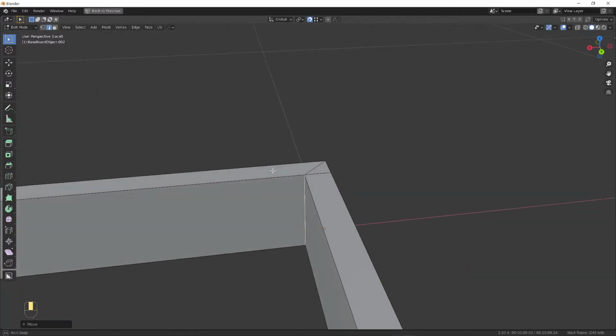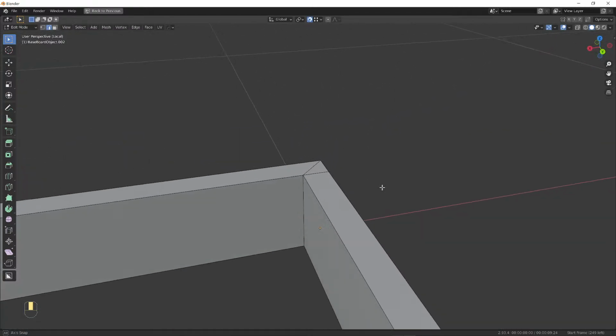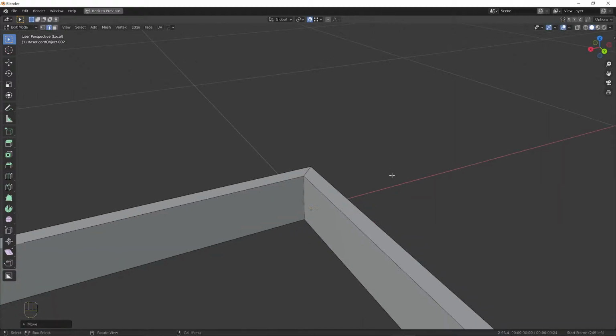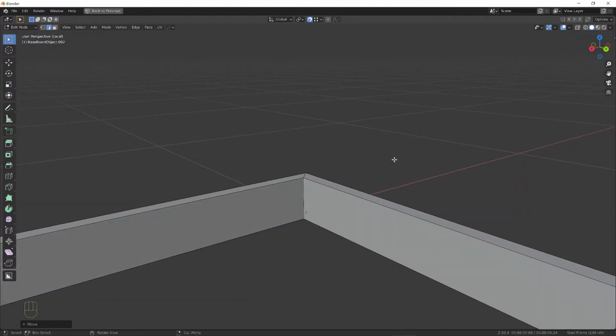Okay, I'll do the same thing here. Select this. I'll press G, in this case X, to move along the X axis. And then I'll hover at the vertice that I want to snap to, in this case this one. Okay, I'm going to press Ctrl A here to select everything, M, and merge by distance. Okay, removed 3 vertices, this one, and that one. And now if I test this, you can see that these are all connected.